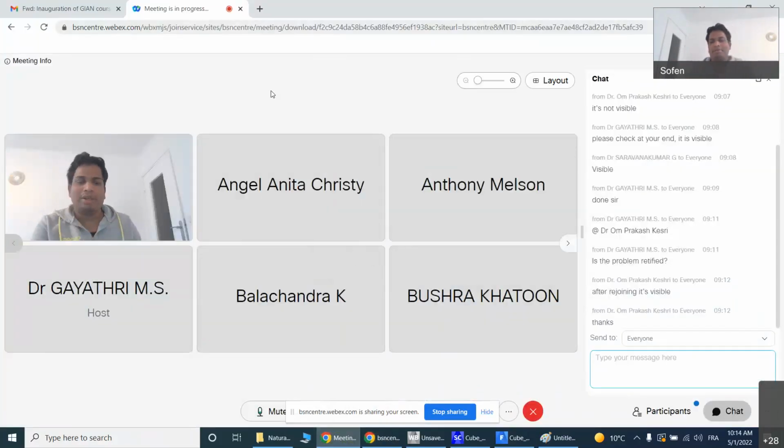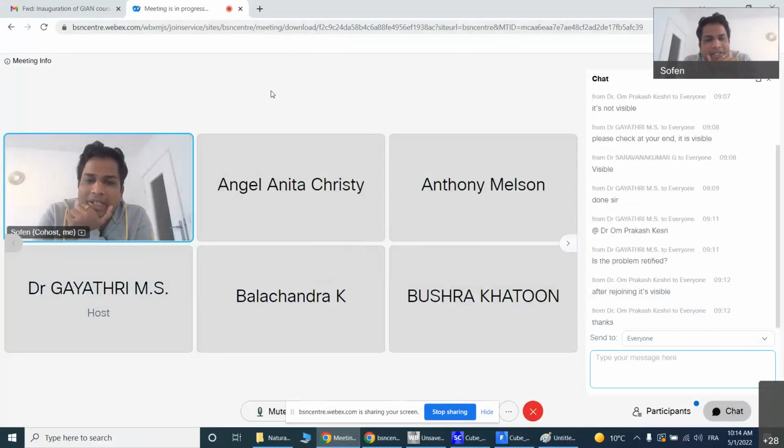So I think we come to the end regarding natural convection. Make sure that your Rayleigh number is more than 10 to the power 6 or 7, in between which transition occurs from laminar to turbulent flow. If your Rayleigh number is more than 10 to the 7 or 8, it's going to be a turbulent region.